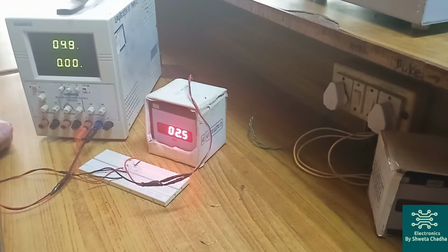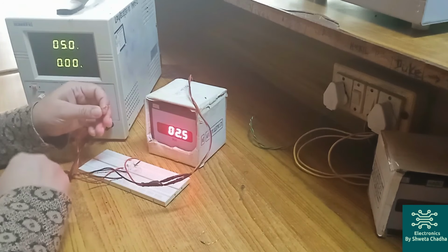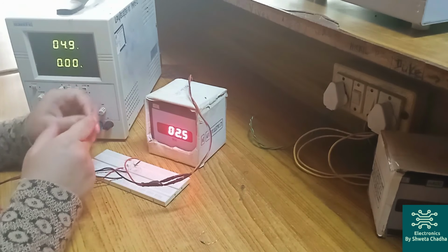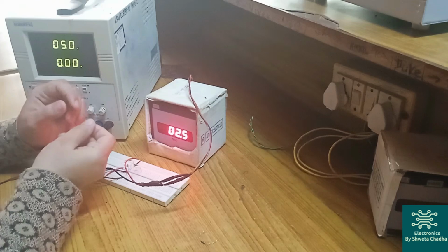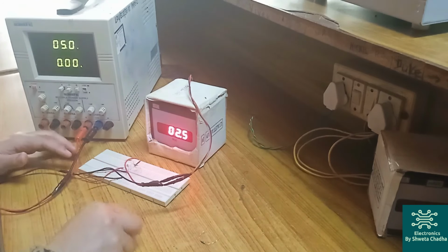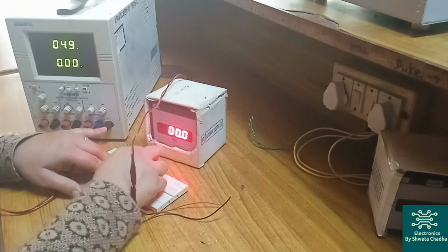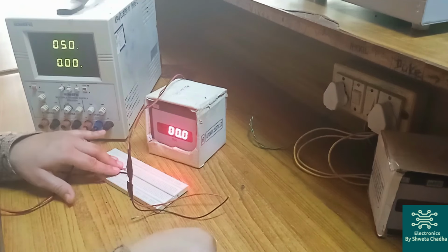This is VTH. Step number 3 is the calculation of RTH, and it will be done manually. RTH comes out to be 330 ohm. What will be the color coding for RTH? This is your RTH: orange, orange and brown. So this is the color coding for RTH, 330 ohm. Now let us design the last circuit diagram. Let me remove all the previous resistances.